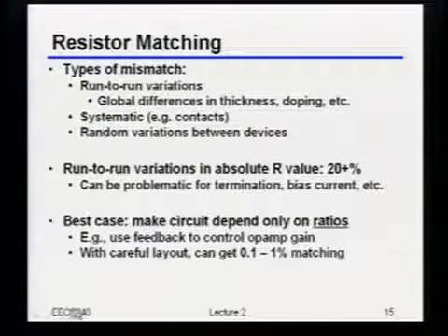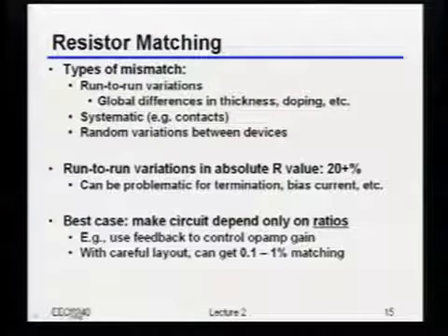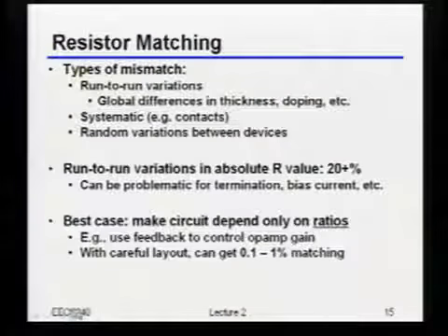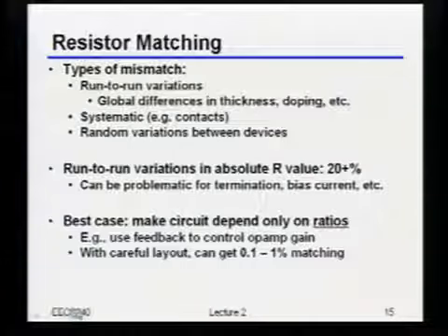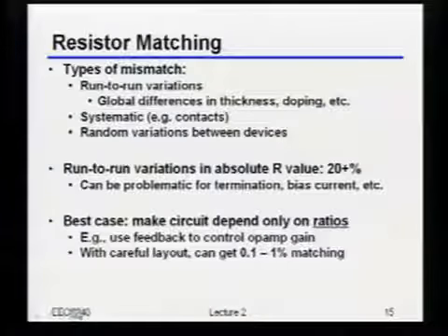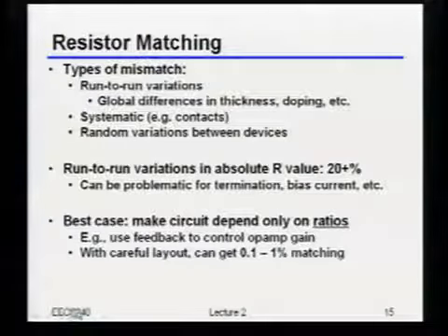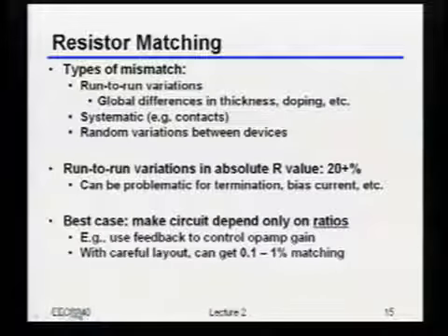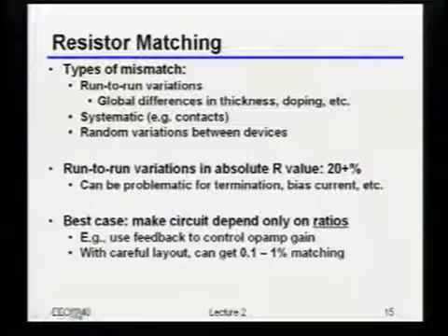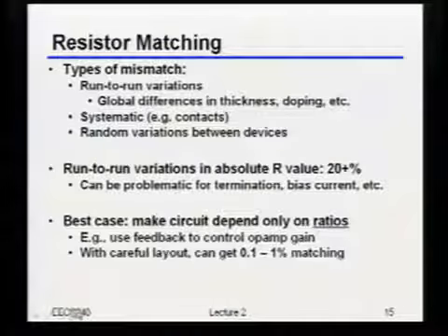Okay? So again, if I just took some resistor and I built it on a chip and I fabbed 100 or 1,000 or 10 million of these chips, and I looked at the value of those resistors, what you'd actually see is some kind of Gaussian distribution. Sometimes it's not even Gaussian, but you get some sort of distribution there. So you never get exactly the value you wanted, but you get some variations around that.